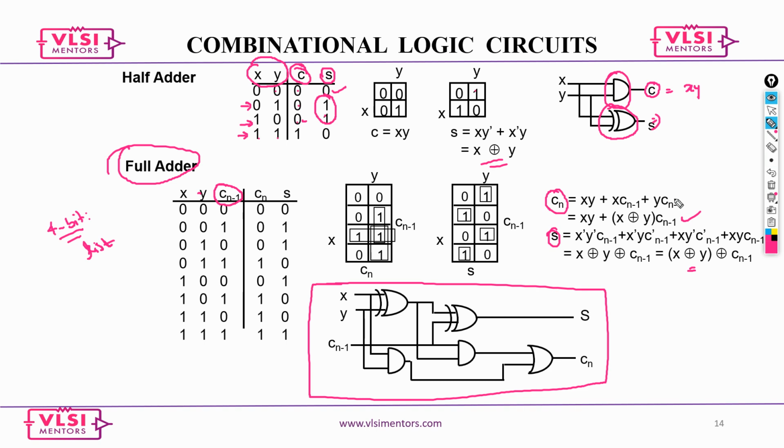Say once you are in industry you would start contributing something. Some people might ask, okay, can you compare these two runs and tell me which one looks good in terms of what? So all that matters. I want you guys to list different types of 4-bit adders and then tell me which is good and for what purpose. Say for example, in terms of performance, I am looking at a very efficient adder. Say I want to hit 3 gigahertz, then which adder will help me? So you need to look at what the logic depth is, how many registers there are, and so everything that you need to look at.